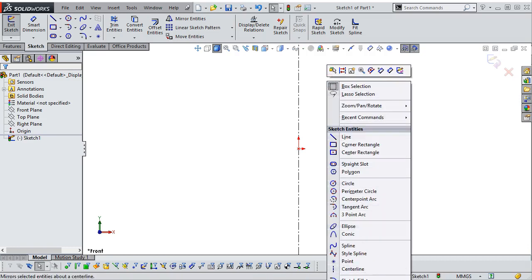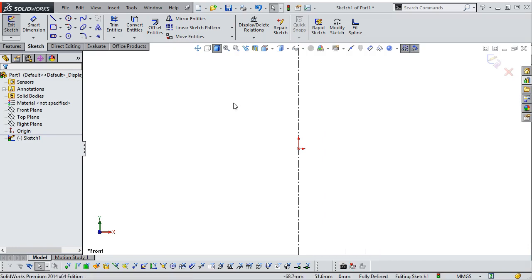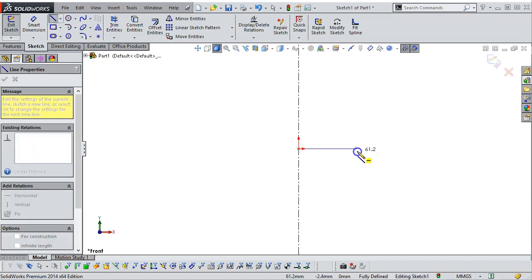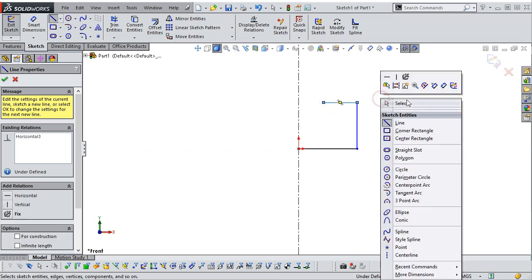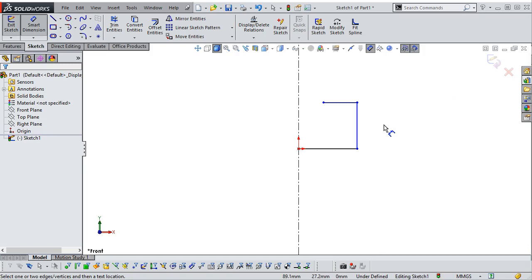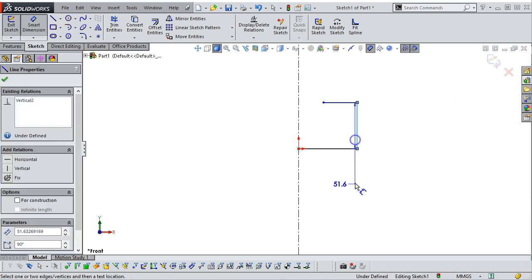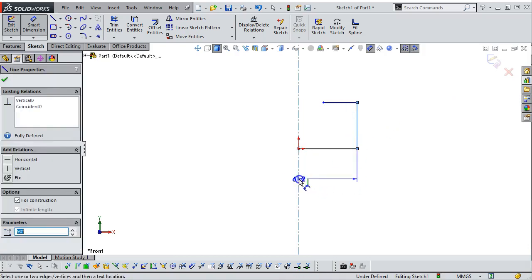And right mouse button, sketch tools, other items that we're seeing. The icons may have changed a little bit. Colors have definitely changed over the several versions. So anyway, for a thin feature, we're going to sketch, and then I pretty much don't have to close this in. I'm going to rely on the thin feature to do it for me.